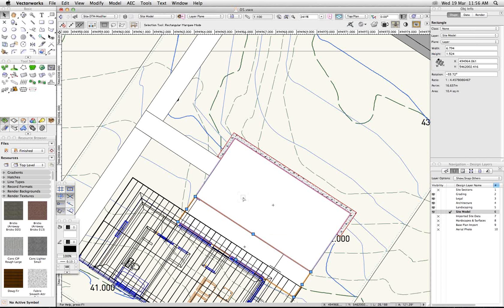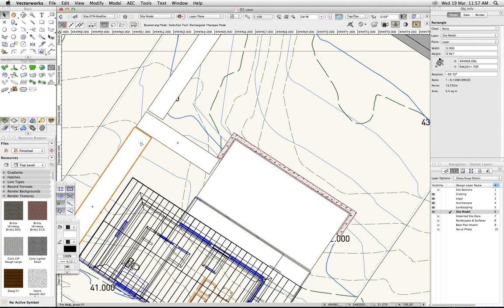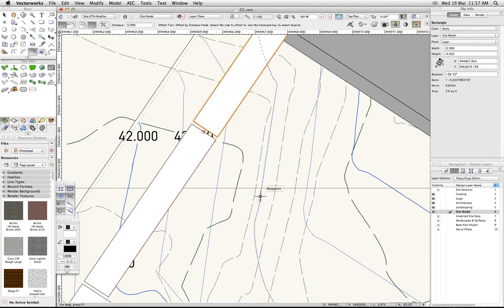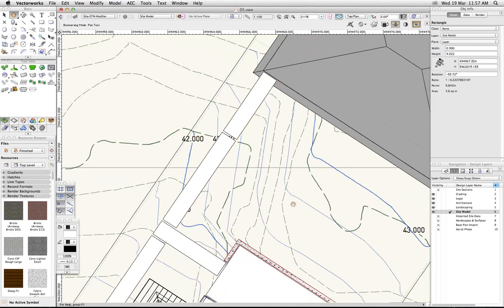So again, building up to just converting all of these to site modifiers, I'm simply going to do a small offset to make them all a little smaller, and then I won't have this problem. So I'll just click. I've offset the original, keeping it a little bit smaller, and I'm just moving around here. I'll select that one and offset, select offset, select offset, select offset, and then the final one. And it doesn't matter one bit that there's a tiny bit of space between them.